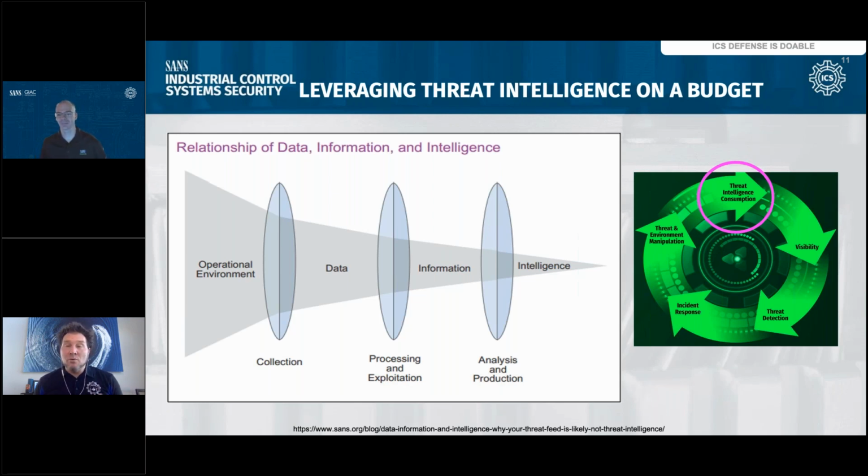which gives you that threat intelligence. So as an example, if you have a honeypot on the internet and someone scans port 502, that does not mean that there's someone targeting industrial control systems, because 502 is a Modbus TCP port. With the context though, if it's specific only to Modbus TCP ports or similar types of ports, then that could be different. So that context is required. Quickly, you're seeing now at this point that context requires humans in the loop in threat intelligence to consume the information and apply the context to give us threat intelligence.